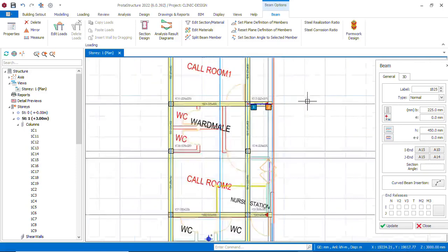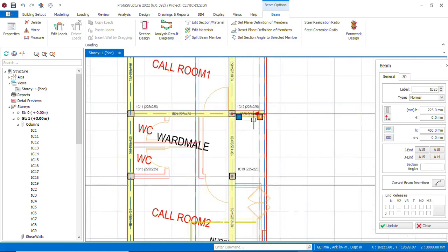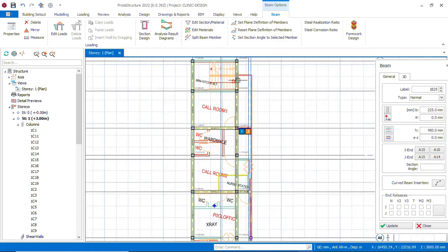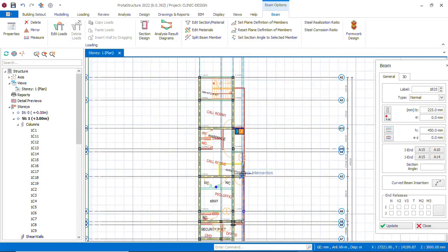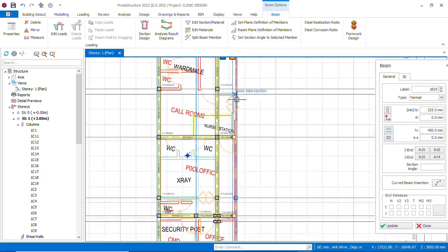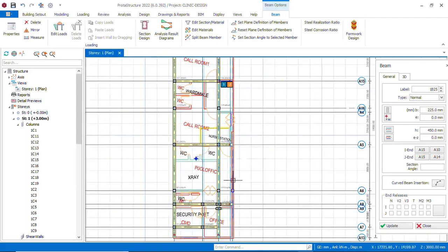These beams, they go straight to the cantilever because I want my cantilever to have a beam under. So you can choose to make the whole of this 1.2 meter the pure cantilever slab. Or you may choose to have only here or here as a pure cantilever slab, and then maybe here that there is wall, where wall is starting, then you may have something like this, a wall.